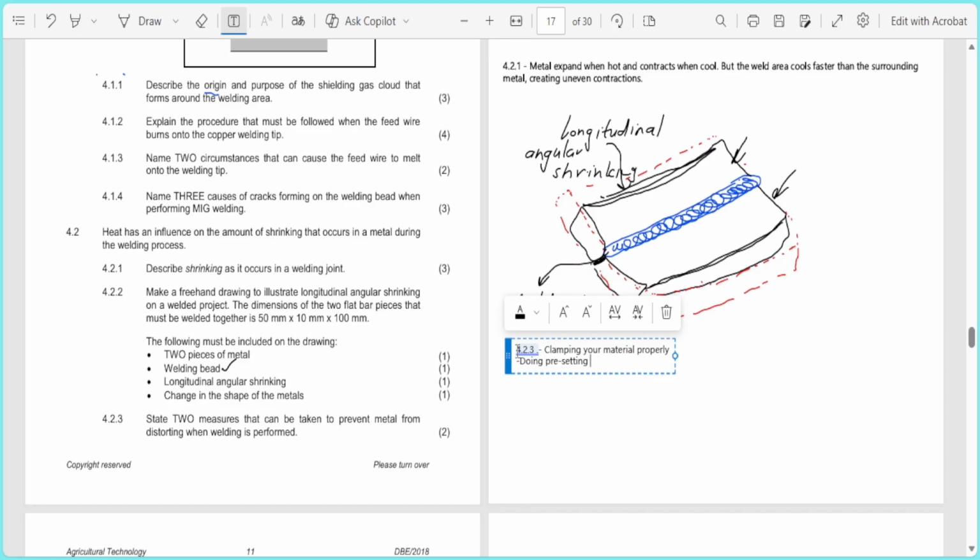Sort of like misaligning them, so that once the welding is done, the welding is going to give them the correct position. It's going to put them into a better position, right? On the other side, the clamping is going to hold everything rigid during the welding.